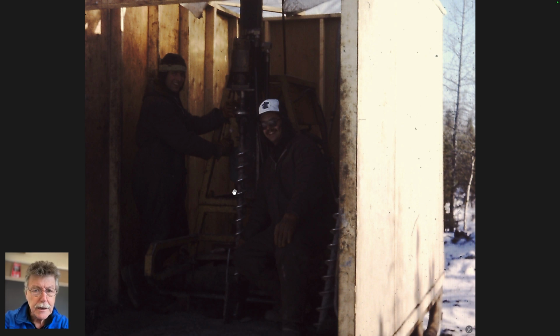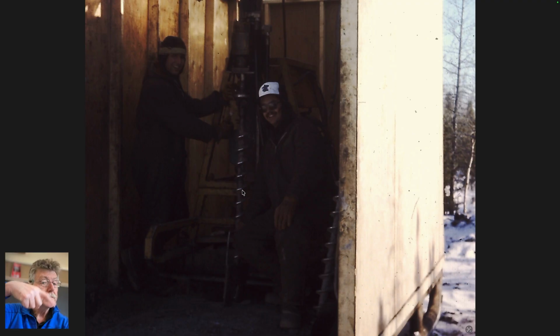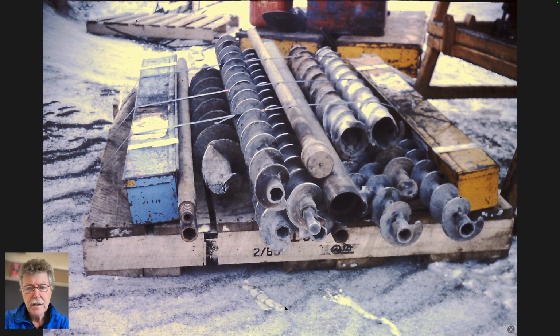So this is the same rig, again vertical, this is the power. This actually has a solid stem auger on it, which is being wound into the ground. And so this would be perhaps in the beginning of the hole to get through the soil first before you hit bedrock. And then once you get into bedrock, to set it up with the rotary core that we talked about. Actually, this might be off the river. This is on the banks of the river, but drilling through permafrost in this particular case.